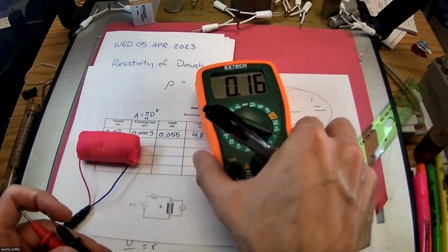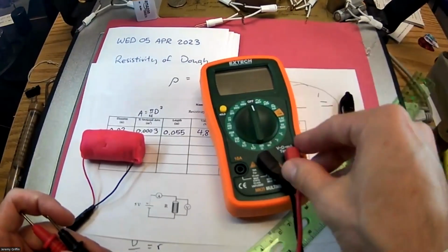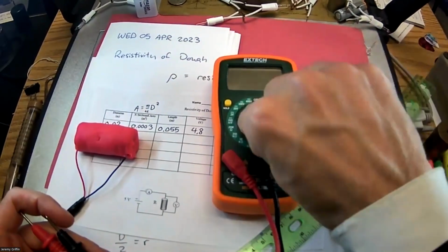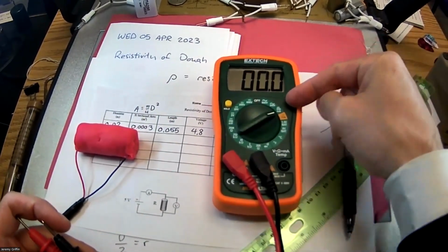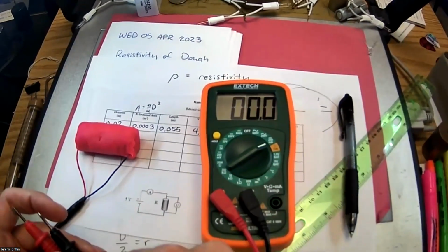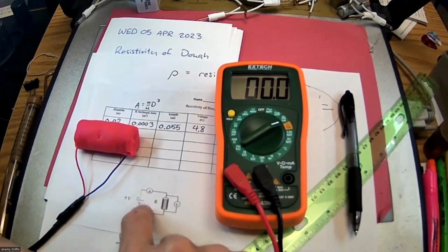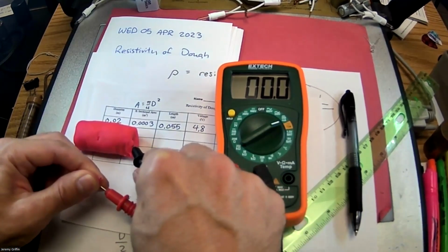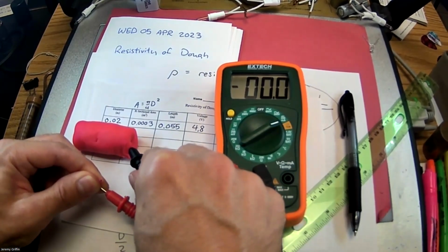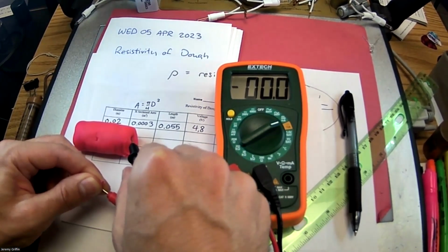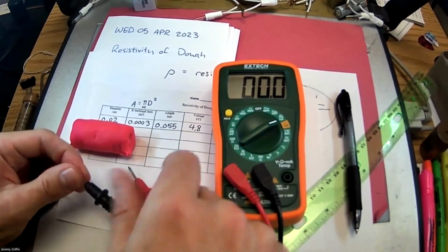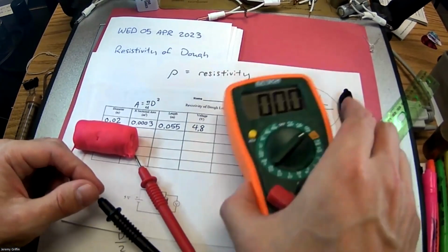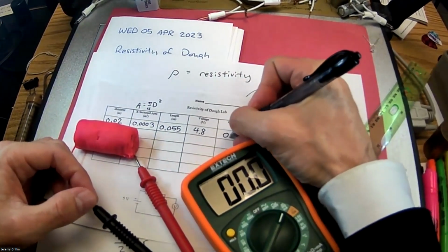What is the current in amps? Now, for current in amps, I have to make a few switches. So I'm going to pull this out, switch it over here, current in amps. All right, switch this toggle to right here. Okay, all good. And then the other thing I have to do, exactly as it shows in the setup, is break open my circuit and force the current to flow through the multimeter. Ooh, it's small, but it's just registering. About 0.1. If I flip my leads, all right, let's call it 0.1 amps. You guys see 0.1? So it barely registers. Let's call it 0.1 amps, right?